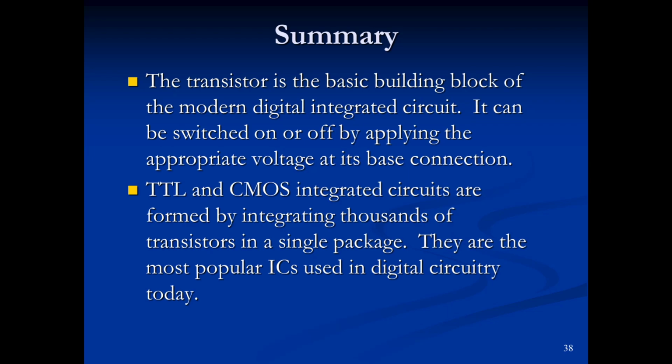We touched on TTL a little bit, and CMOS integrated circuits. They're two systems that do the same thing. They just use different transistor technologies inside, but they behave the same way. They create the same logic. A TTL inverter is the same as a CMOS inverter. It's just that there's trade-offs between each of the systems. These two systems are by far the most popular ICs used in digital circuitry.